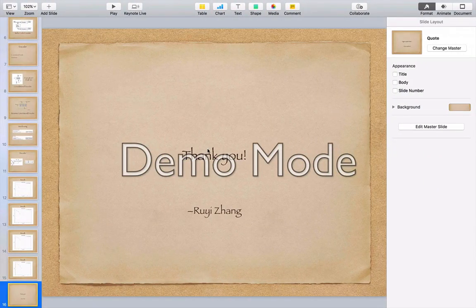I use random input data and display the BER with different iteration numbers and different code block lengths. The turbo code is an important channel coding method which pushed wireless communication into another level. It is the first coding method that closely approached the channel capacity. It is used in 3G and LTE. This technique has already been simulated and used in real life, though it still has some drawbacks.